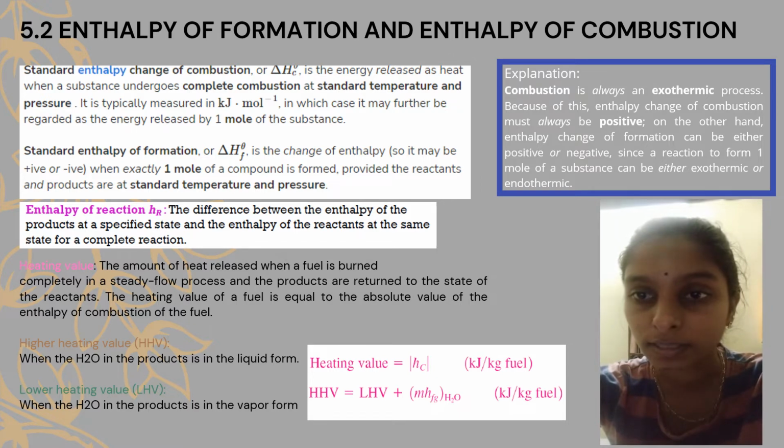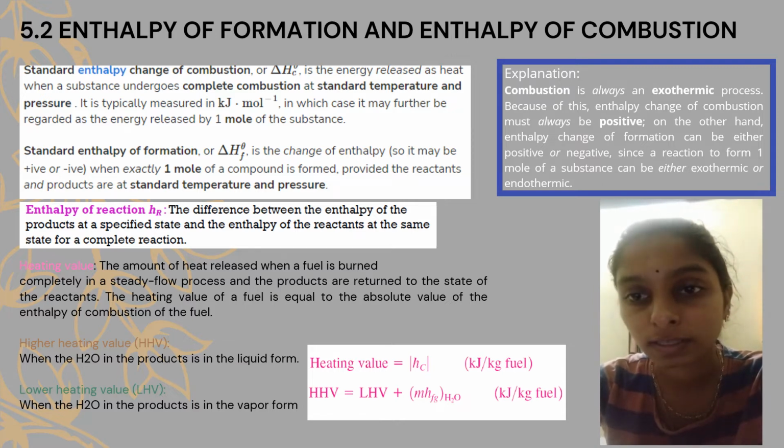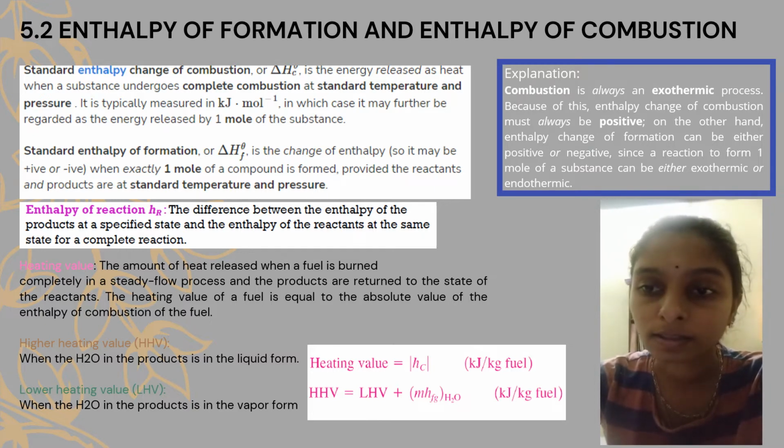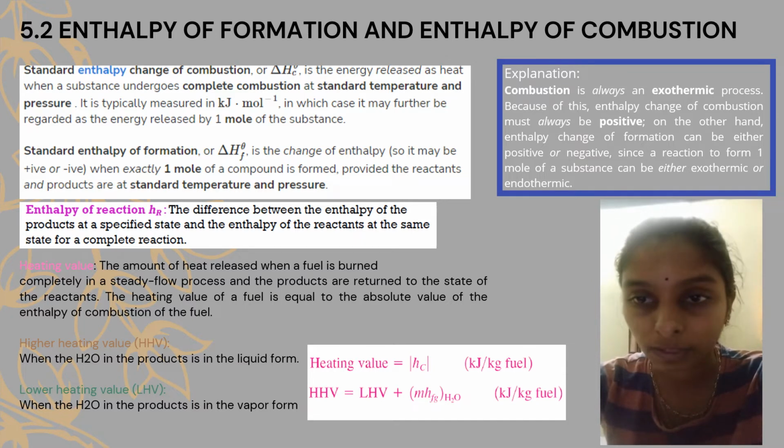The next is heating value, the amount of heat released when a fuel is burned completely in a steady flow process and the products are returned to the state of the reactants. The heating value of a fuel is equal to the absolute value of the enthalpy of combustion of the fuel.